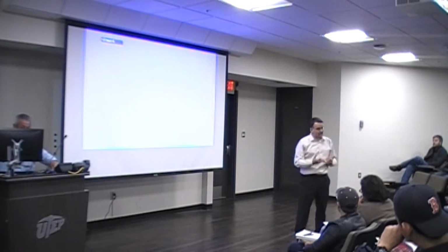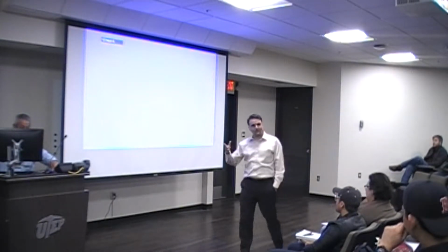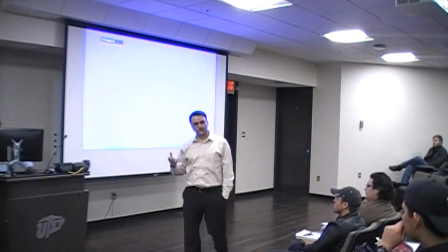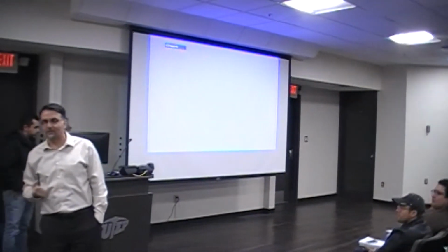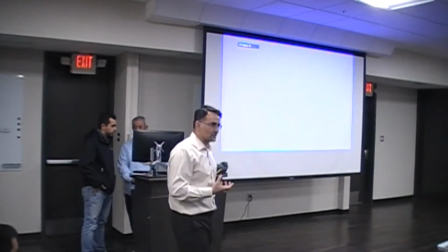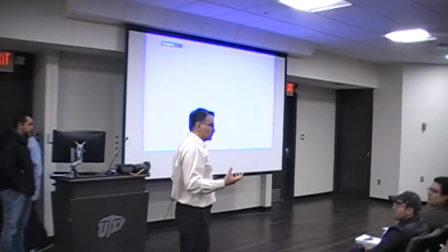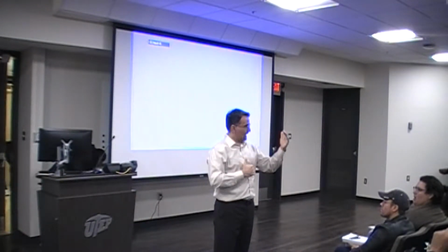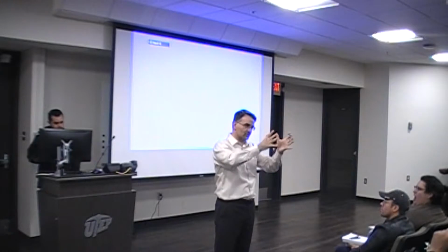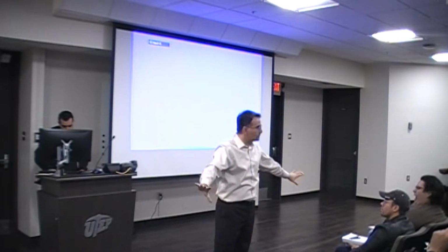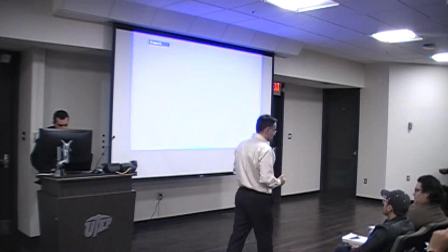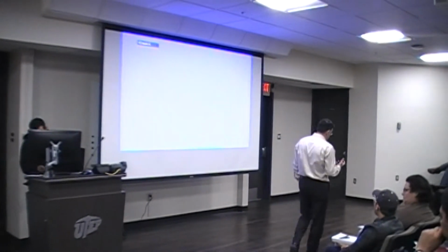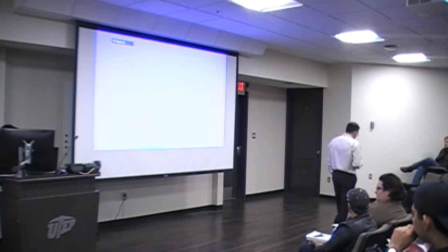So you have to distribute those loads, and that translates into the concept that you had in your structural design, mechanics of material, and concrete design, which we called the dissipation of the energy, or dissipation of the loads, right? So if you have multiple layers, or that platform, it transfers the load into the platform and distributes it in the soil. It brings it down to the level that the soil can tolerate. That's what it means in terms of the loads.